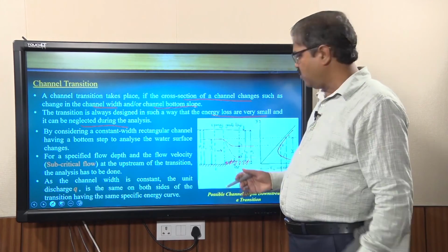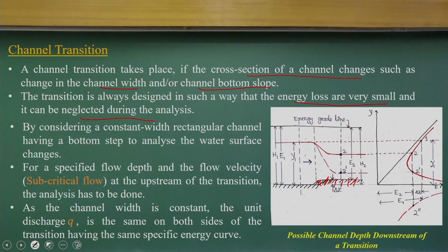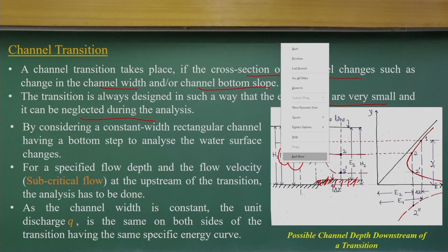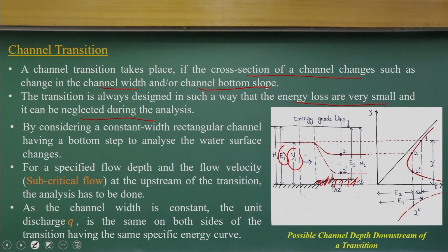So, in those flow conditions, there is a flow coming which has flow depth y1 and specific energy. As we consider the channel horizontal, you can find the specific energy, and the total energy is the same, H1 equal to E1. You have y as the flow depth and delta Z as the rise depth, the equivalent rise.